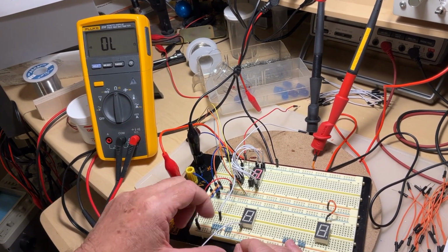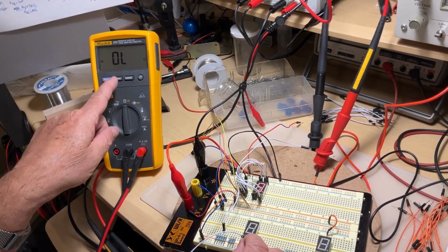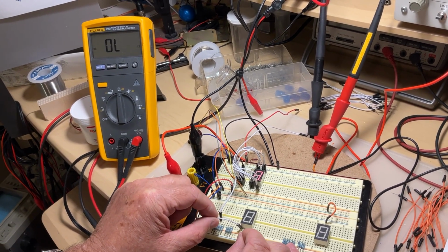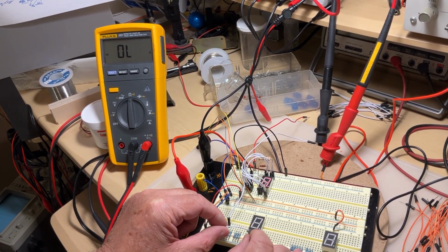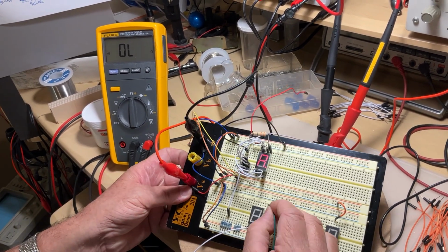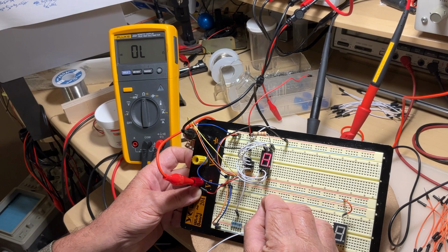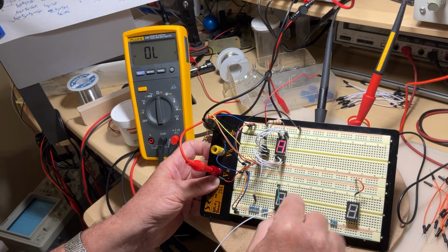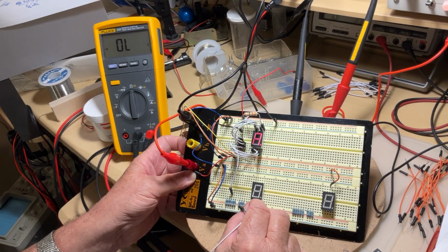So I have one wire on the pin 1 and I connect the second one to the pin 2. I can't hear any sound, it's overload. So if one common is here, the second common is surely not on the second pin. I go on the third. No common. On the fourth, no common. On the fifth, no common. Now I pass on the other side: 6, 7, 8, 9, and 10. There was no connection between the pin 1 and any other pins around the package.